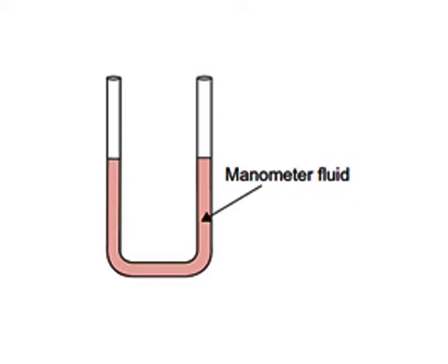Let us first consider how a U-tube manometer is used in measuring pressure, then we will examine its use in flow measuring devices. A U-tube manometer is a small diameter tube of constant diameter shaped as a U as shown in figure 3. The tube is partially filled with a fluid called a manometer fluid, rising to a certain height in each of its arms. This fluid must be different from the fluid whose pressure is to be measured. Mercury is commonly used as a manometer fluid.